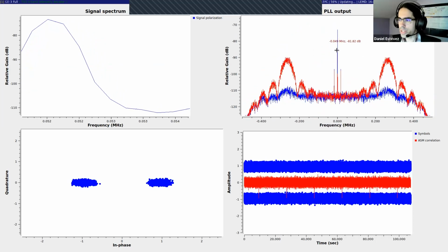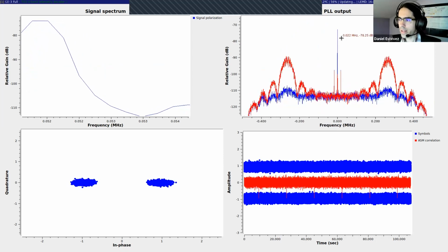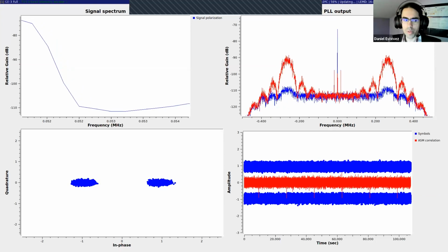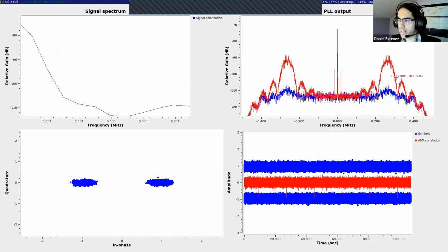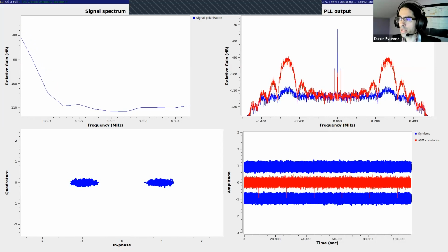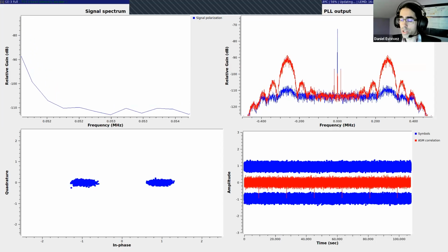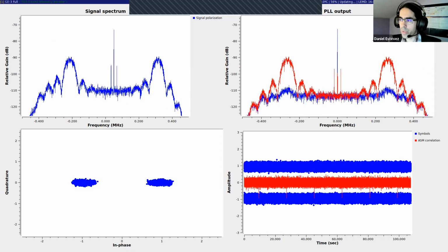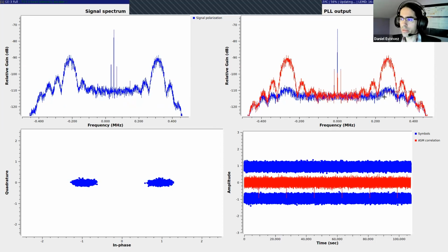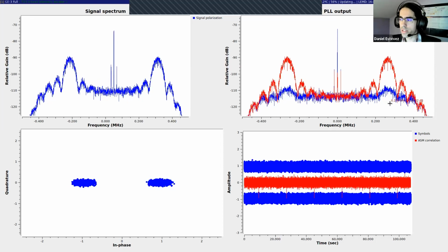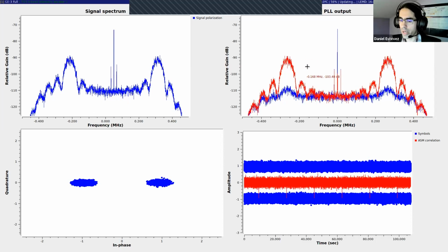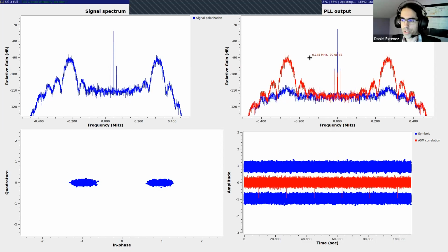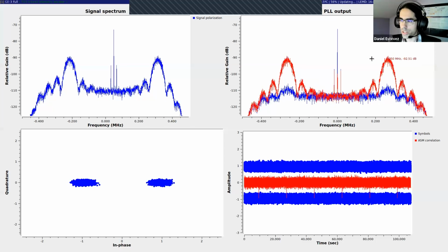The second thing we notice is that the residual carrier is depicted in blue. This means the I part or real part of the signal. The data subcarriers are depicted in red. That means the imaginary part or Q component of the signal. And this separation between the real part and imaginary part, between blue and red, is what allows us to combine these two subcarriers back and obtain this 50% signal to noise ratio gain, compared to processing just a single one of those.